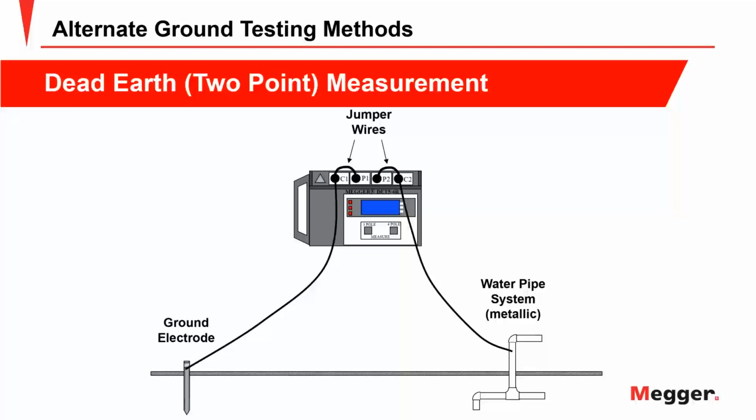In the old days, people put in shunts or even paper clips would work. With newer equipment, you don't have to do that anymore. Your new modern testers will, by a selector switch position, just do the shunting internally. So you just flick your selector switch to a 2-pole position and run your leads out and go from there. So it's a pretty simple test.